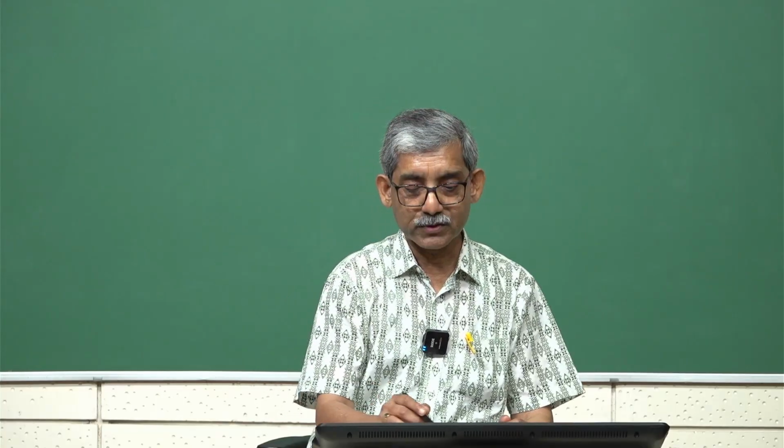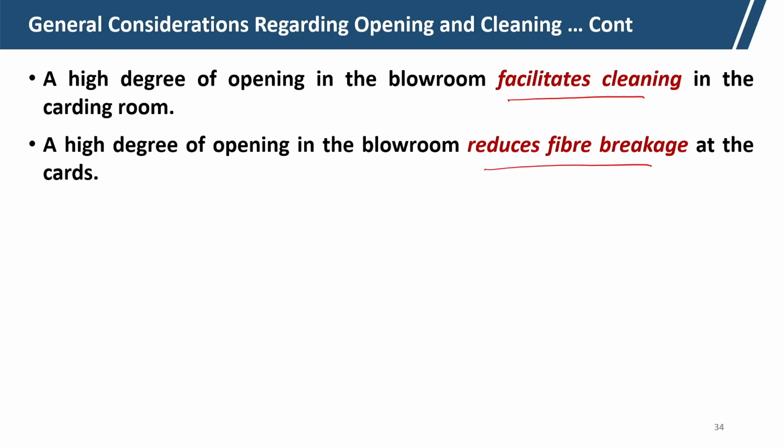A high degree of opening in the blow room reduces the breakage at the carding. So, if we can open the fiber properly in the blow room, then when it comes to the carding, under the action of the pins, the fiber breakage will be reduced.